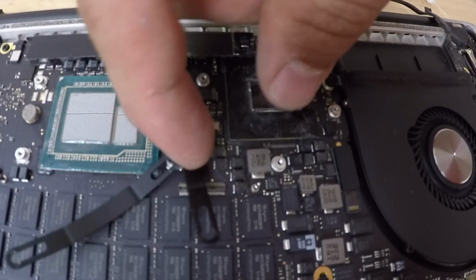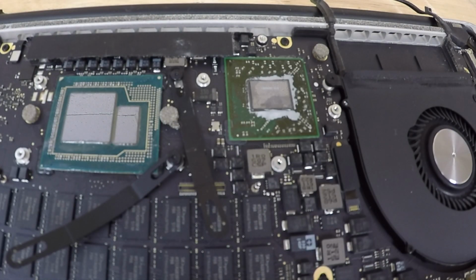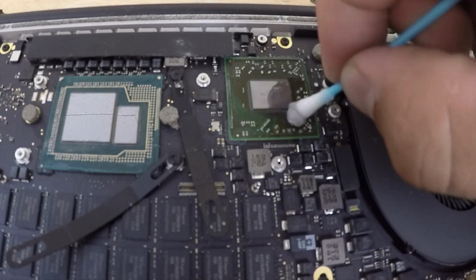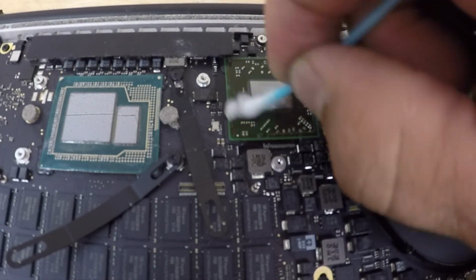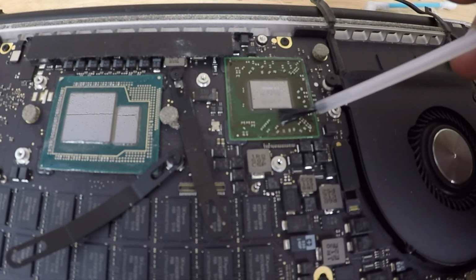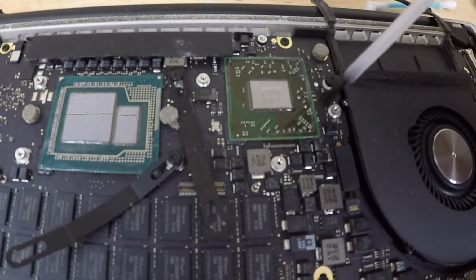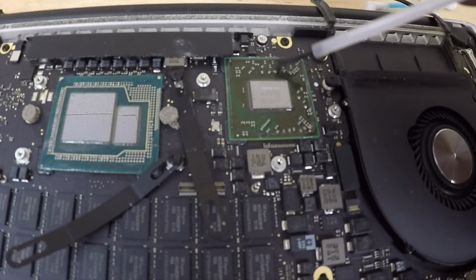Now I'm going to remove the tape off the GPU die so that I can clean off the remaining thermal compound that is on the chip. And I'm going to make sure both the CPU and GPU are clean now. Now I'm going to add the conformal coating and add several layers to the GPU chip so that no liquid metal will cause a short if it touches any of the connectors.